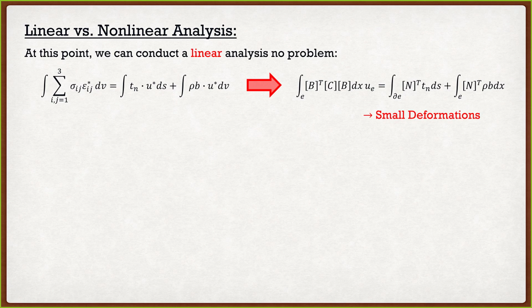Remember when we did the assignment and we rotated that rectangle, or that plate, whatever you want to call it? Now, when we do rigid body rotation, I'm not straining anything. If I were to take my little clicker and just rotate it, I'm not straining it. It's not in tension, it's not in compression. All I'm doing is rotating it. But due to our small strain matrix, we actually predicted some strains, especially once we got into large rotations. And we know that this is actually incorrect. So small deformations bite us because we're limited now to very small displacements.